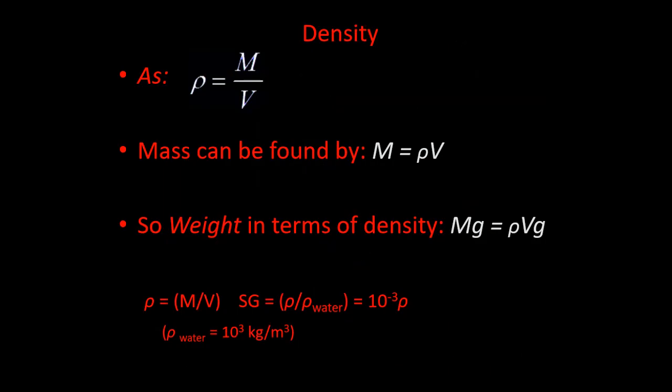So we can use the density quite often to find the mass of our fluid. So ρ is m over v, m can be ρ times v. Something to keep in mind is there is a difference between the mass of our fluid, the mass of what we're looking at, and its overall weight. Remember, a weight is a force due to gravity. Anywhere we see a weight means we have to take our mass and multiply by a factor of 9.8 meters per second squared, mg. So m times g is equal to ρ v times g.